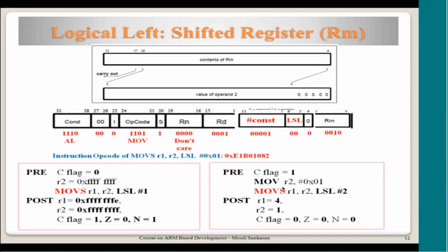Now what is the position here? Also the instruction says I want this to affect the carry flag or zero flag or negative flag, and then R2 is filled with a 01, and that is the operand RM, and logical shift left by 2 positions, that is 1 is moved to the 2 position, that means 100 it will become, right.